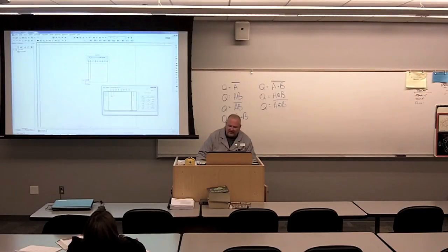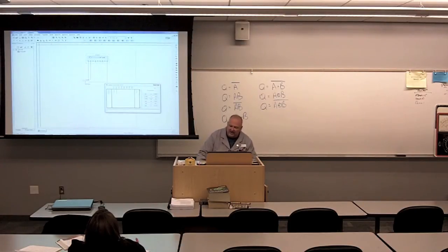So you see how it gave me the correct answer? A 0 and a 0 gives me a 0, a 0 and a 1 gives me a 0, a 1 and a 0 gives me a 0, and only a 1 and a 1 gives me a 1. So it just gave me that equivalent. Now the nice thing is, once I have it in here, I could go truth table to Boolean expression by clicking this tab. So I'll click on this tab and look at what it gives me down below in this queue. I know it's really small on the screen, but you see the A and B?